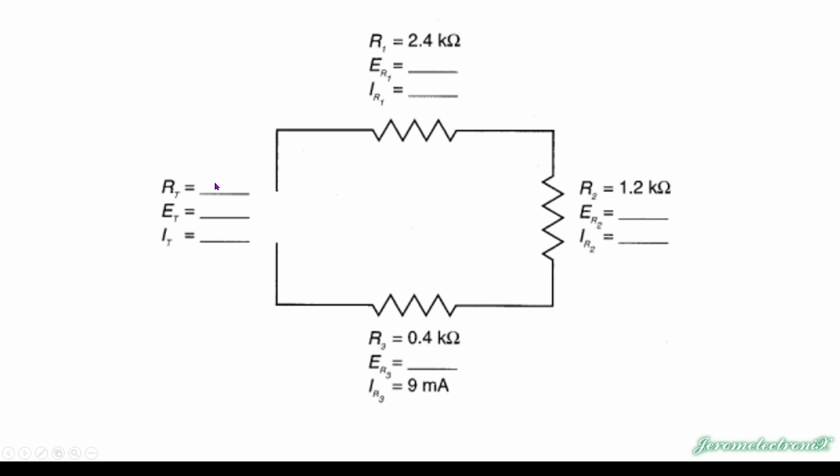We know all the ohms. We know all the amps. Ohms, add them up. Amps, if you know one, you know them all. And volts, they're usually add them up, but we don't have any of them to add up. So we can calculate each one of those using Ohm's law, putting in the 2 pieces of information that we have for each one of these, and finding the volts at each location. Add that up or use Ohm's law again here, and that will give you the total.